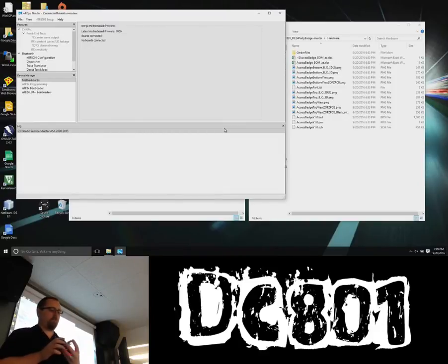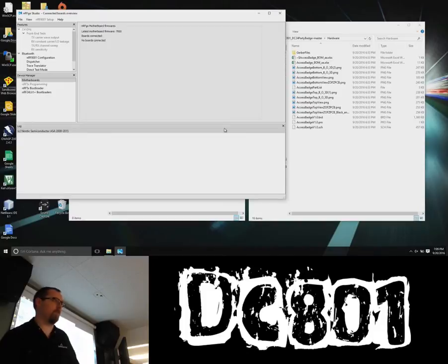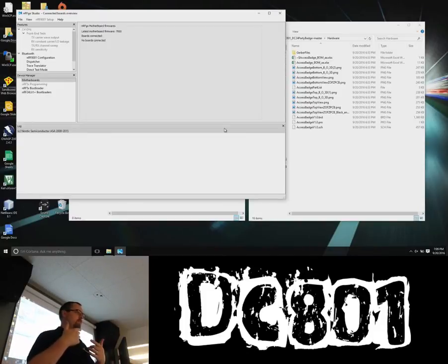And then the BLE module, we have it set up as an Eddystone beacon by default, so it broadcasts a URL. On certain smartphones, some of the newer ones, will auto sense the website and will give you a notification at the top. You click on it, it'll take you to the website that the badge is broadcasting. Or you might have to download a beacon reader off of the Play Store or the Apple Store, whichever one.